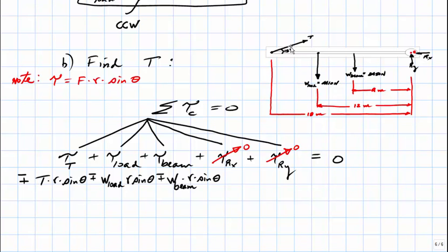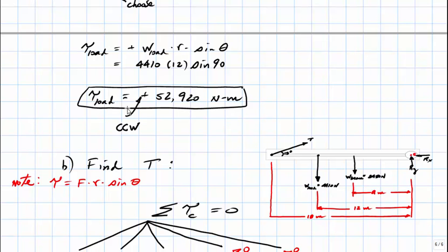The tension is creating a clockwise rotation on the beam. If the only force present was the tension, that tension, of course, tends to want to pull the beam in this direction. And by pulling it in this direction, the beam would rotate in a clockwise fashion. Therefore, we have to select a negative sign in front of the torque, which represents the tension. The torque of the load was already evaluated. We already noted that the load tends to produce a counterclockwise rotation on the beam.